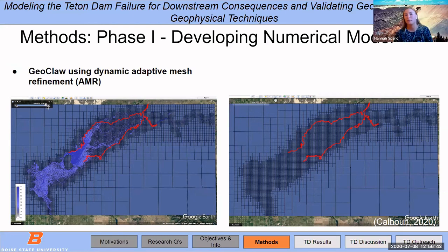That's a good question. I will be able to better answer it this fall. I'm planning on doing the Manning roughness structure for photogrammetry campaign in August, September, but I can also combine that with recent LiDAR surveys, and by recent I mean within the last 10 years, in the area to define which variable regions would require what Manning's coefficient would be necessary. I know other software like Anuga and HEC-RAS do already incorporate surface roughness, so I'm also planning on looking into those to see how they institute it, so I can hopefully have fewer errors initially and it'll be a smoother process. But I am planning to look at flow depth also when instituting this roughness coefficient. The project isn't quite there yet, although I'm quite excited about that part of the project.